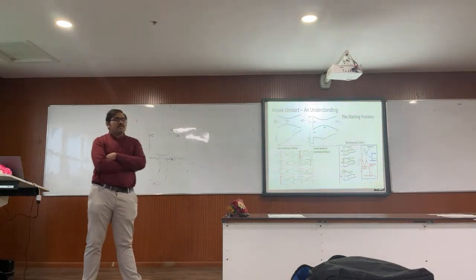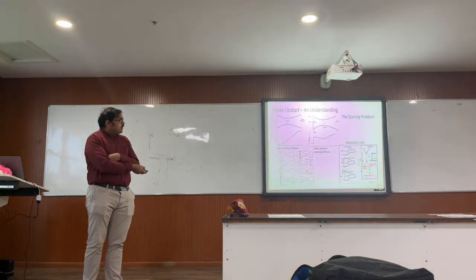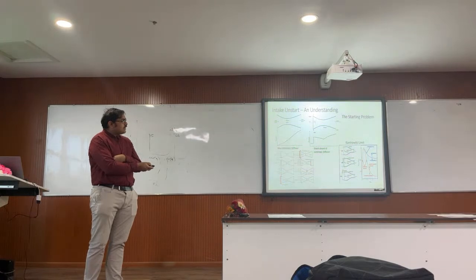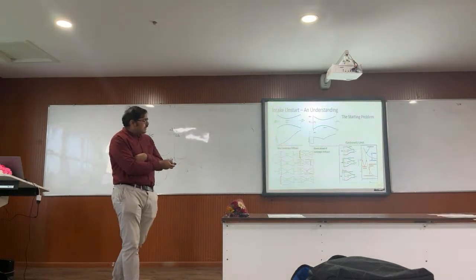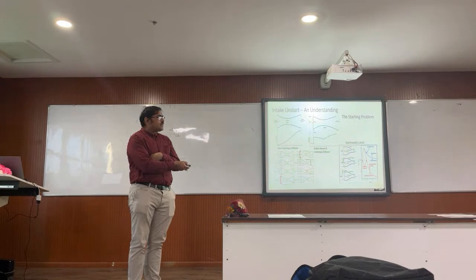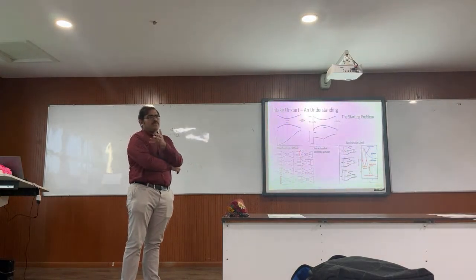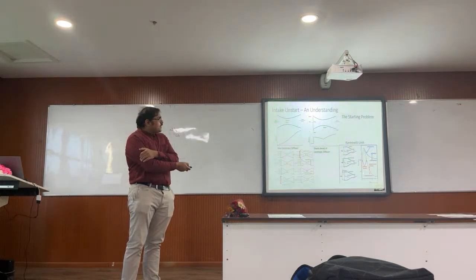But that is a condition that we have to design for, and that condition is what is given by controls. So you can see there are two curves over here, a dashed red curve and a blue curve. The blue curve is the controls curve, where if you have these minimum areas above the controls curve, then the likelihood of an intake starting is always there. It is always starting.